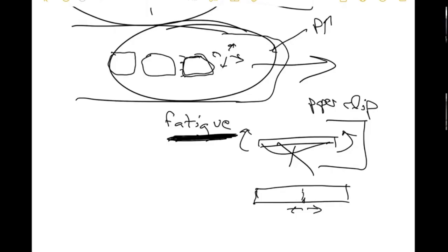Oh my God, it's either 3 years or 5 years. They completely tear everything out of the plane. They take all the seats out and get it all the way down to the fundamental fuselage and frame. They literally have guys that climb around and inspect every single square inch of that thing to see if there are little fatigue cracks, and if there are, they replace those components. That's how big of a deal this fatigue business is.